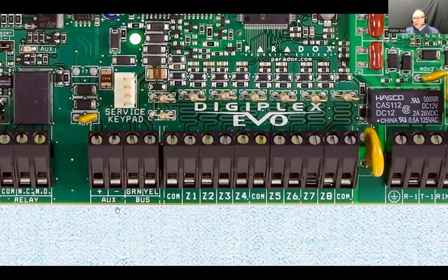So you would use yellow and green when it comes to connecting signals. But you could use the same cable to connect smart devices such as keypads. Then you would connect red and black to the power, and yellow and green as a signal bus. All right. So that's as far as the auxiliary power and the communications bus terminals go.